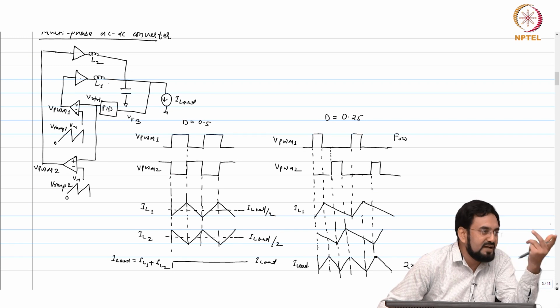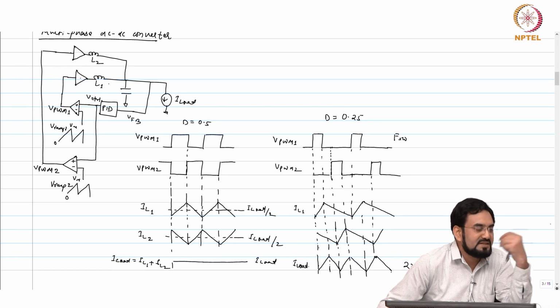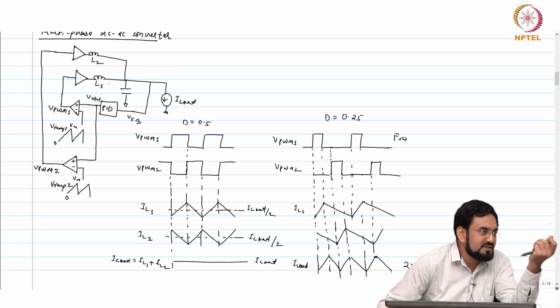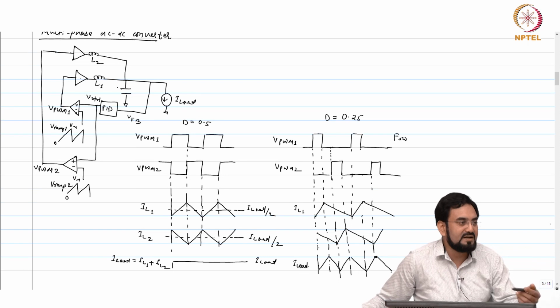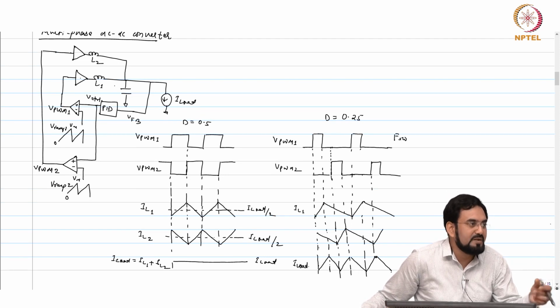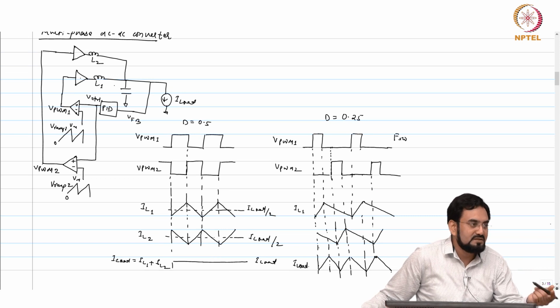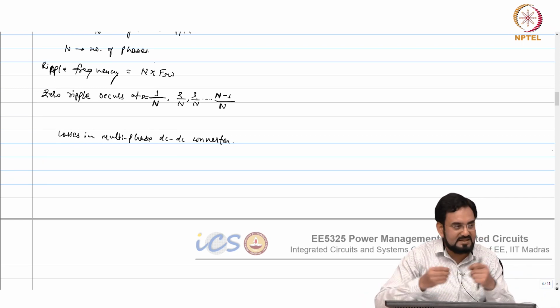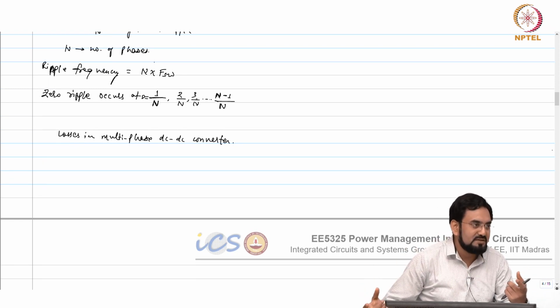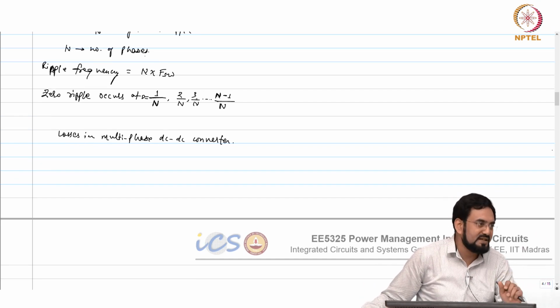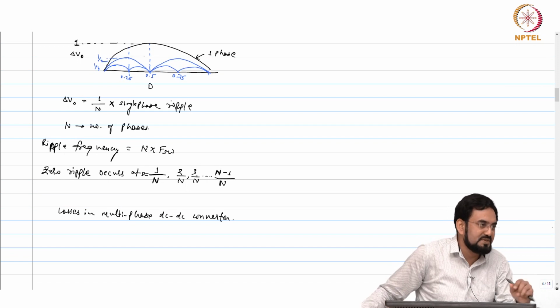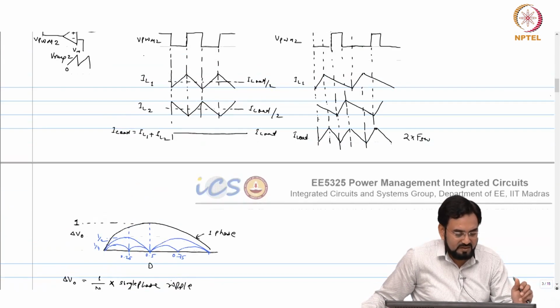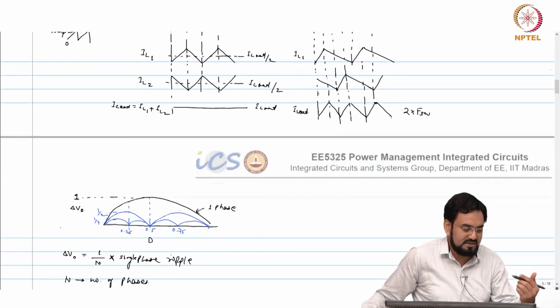So what we can do, we can use a higher DCR inductor that will have a smaller size. Lesser the DCR, bigger the inductor is, because it requires a thicker coil. So low power inductors will be smaller in size compared to high power inductors. So still you can reduce the size of the inductor. Maybe after packaging it may not scale by 2x, but still maybe 20-30% reduction you can still see by using lower power inductors here.